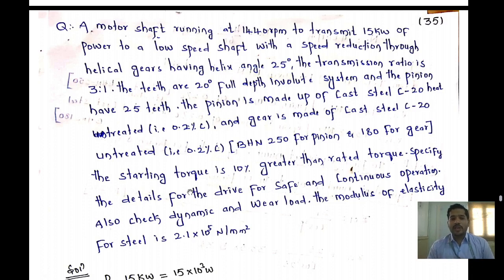The transmission ratio i is given as 3:1. The teeth are 20 degree full depth involute system and the pinion has 25 teeth.